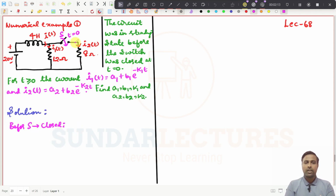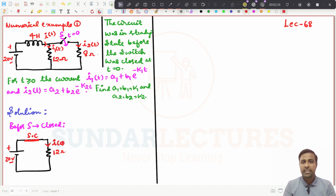Before S is closed, this branch is not connected, and only this circuit is connected, and that too, as we have seen, is at steady state. What happens to the inductor? The inductor will be short circuited. That is what we have seen in the previous class. What will the circuit be now? I have just drawn the diagram, and the inductor is now short circuited. I have taken the current as I of 0. Why am I taking this as I of 0? Because my circuit is going to connect with another resistance after some time. So I am taking this current as I of 0.